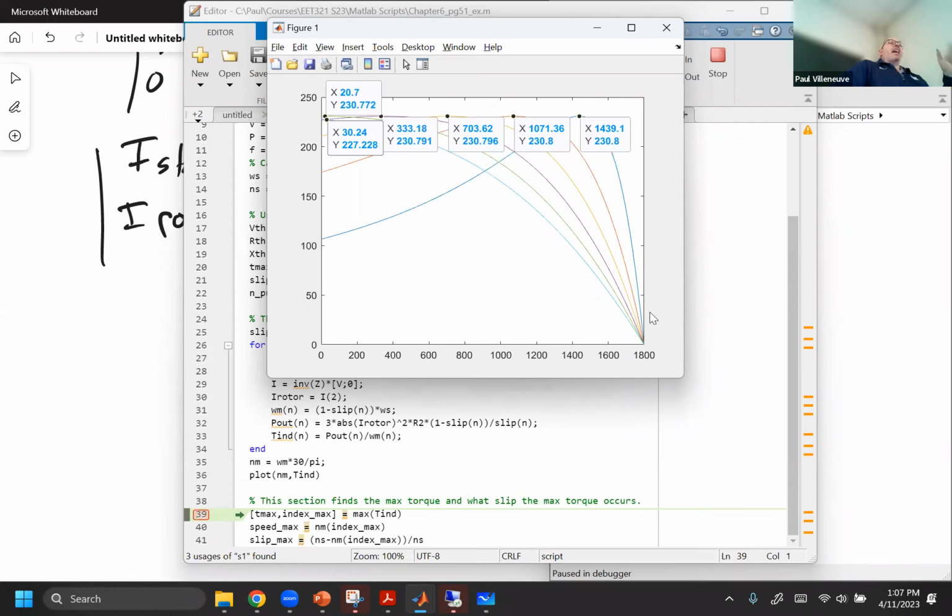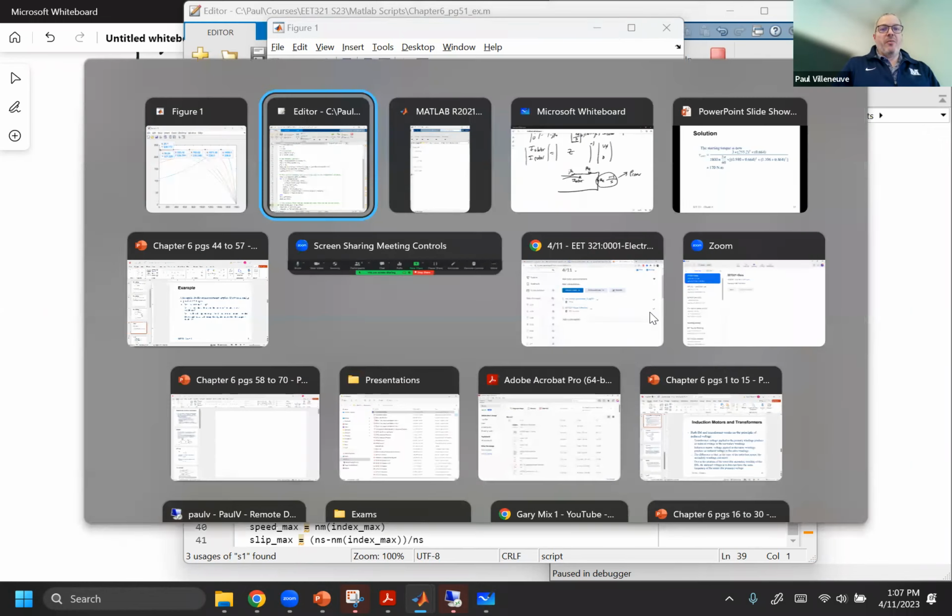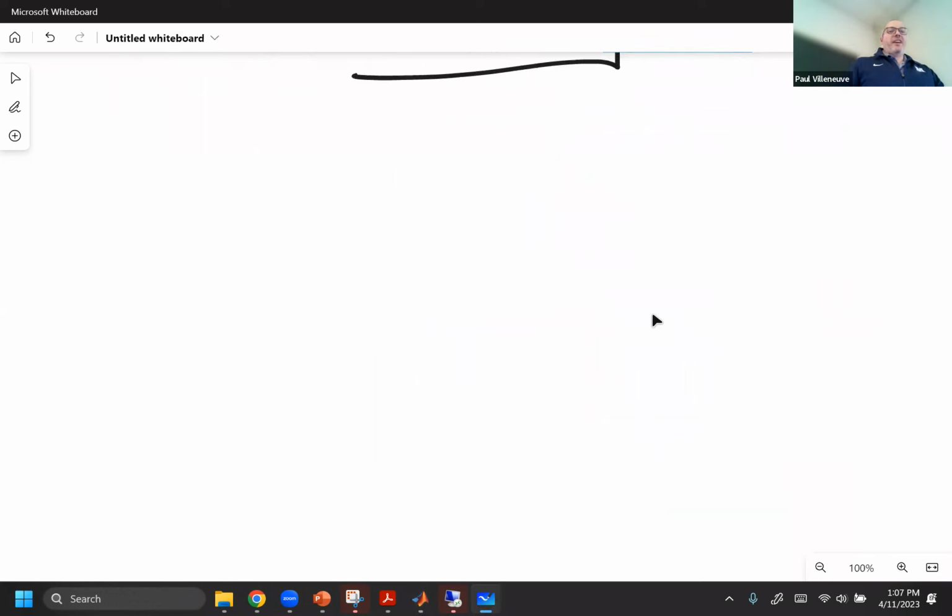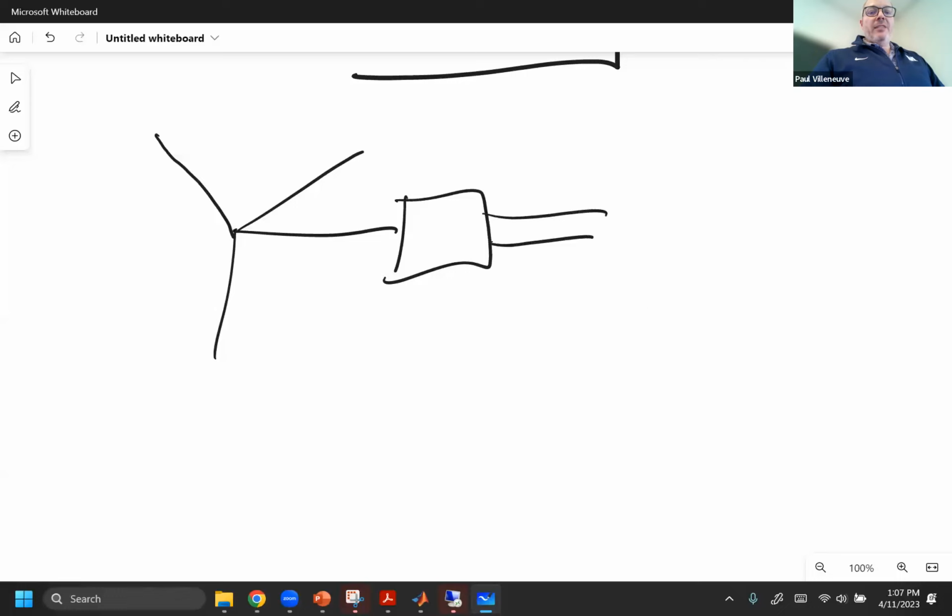So they can either make it additive or subtractive, depending on how fast that turbine is spinning, so that you always produce 60 hertz. So the reason why a doubly fed induction generator is perfect is, if I have a wind turbine over here connected to a generator, the output of the generator, I would love to connect that directly to the utility.